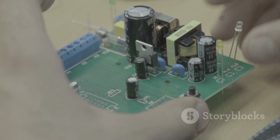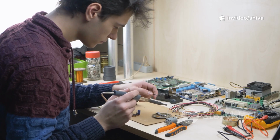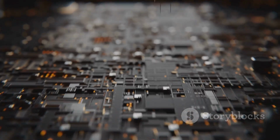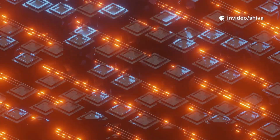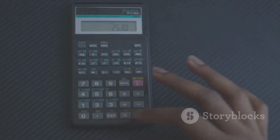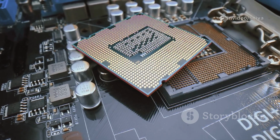So, we've gone from a single switch to a circuit that can add numbers. The final step is one of scale. A single full adder can add 1 column of binary digits. But our computers work with numbers that are 64 digits long. To add 2 64-bit numbers, a CPU simply lines up 64 full adders, 1 for each bit. The carry-out from the first adder becomes the carry-in for the second, and so on, all the way down the line. It's a cascade of simple operations happening at lightning speed, and this is just for addition. The ALU has other sections dedicated to all its other functions.